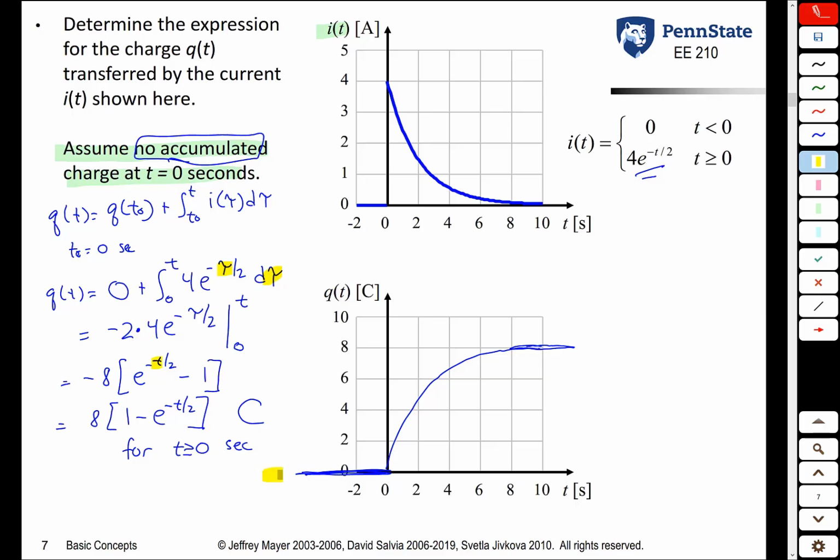Here we have a slope of 0, so once again, the current is going to be 0. All of a sudden at time 0, we have a large positive slope. So that's going to give you a positive current. As we increase in time, notice that the slope gets smaller and smaller and ends up at 0, and so the current starts at a positive number and it stays positive, but it gets smaller and approaches 0.